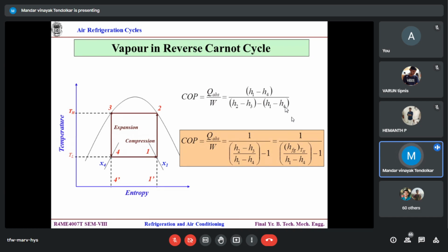To compress an ideal gas, you can deal with it very easily, but for a wet mixture there are practical difficulties like sealing and lubrication. Okay. To execute the isentropic compression, practically that is the problem. That's why I said you can achieve up to 99% of the Carnot cycle, may not be 100% always possible, because executing an isentropic process for an ideal gas is very easy.